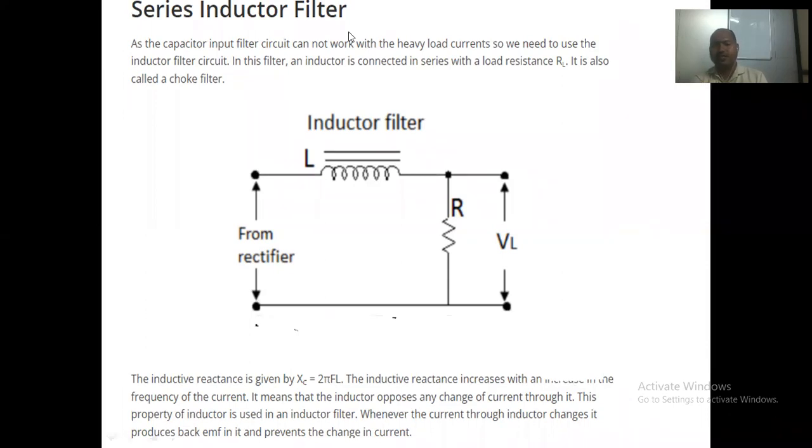In the same way, see, this is the inductor, it is not pure or it is not ideal. Okay, so we know that the inductor must pass only the DC signal, but it has some lacuna, or some problem. That's why it contains some AC components. So whatever the output comes across the inductor also contains some ripple. Okay, so these are the things with respect to the inductor type of filter.